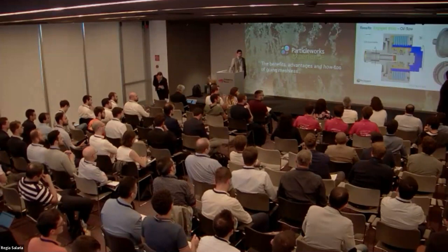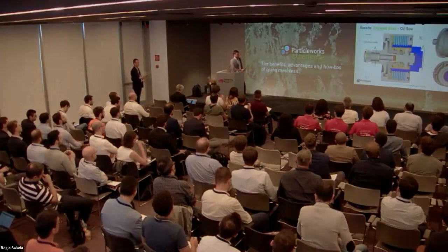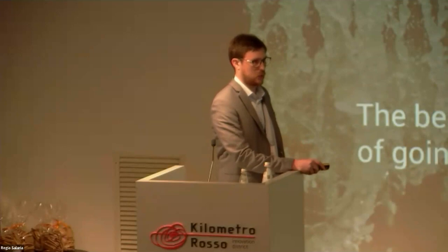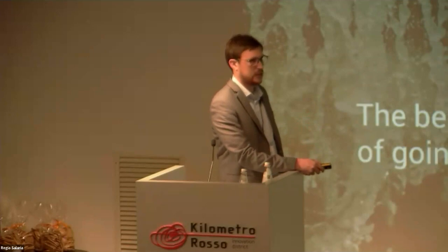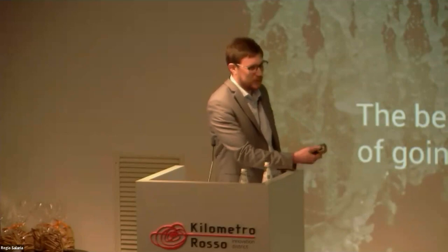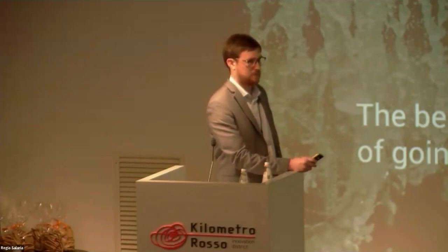How long did it take for the full simulation with 120 million particles? Okay, so this simulation ran about 1 week on multi-GPU. It was 4 GPUs, because also the memory required was high. I think that with the multi-resolution feature, this time will drop, or at least decrease significantly, because in the center region we don't need small particles, so we can refine only what happens inside the disk and in this gap here. Thanks.